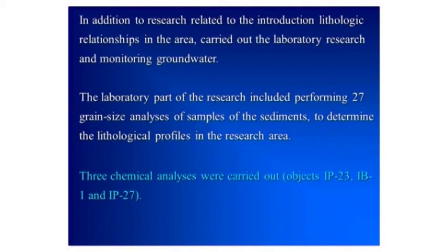The laboratory part of the research included performing 27 grain size analyses of samples of the sediments to determine the lithological profiles in the research area. In order to determine the seepage characteristics of the aquifer, a pumping test was done on the well IB1, while the water tables were also monitored at piezometers IP1, IP2, and IP3, which are located nearby.